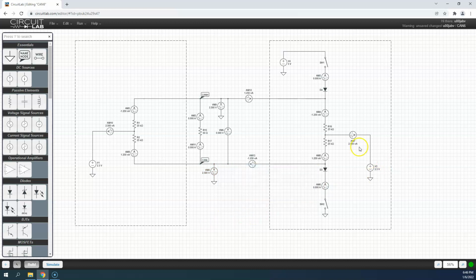But still, there's just a minimal current. This is nanoamps. This is 10 to the -9th. It's very small. It's got a bunch of zeros in front of it. Your meter wouldn't even measure this. You don't have a meter that's accurate enough. A Fluke 87, none of those are going to measure a nanoamp. So we could see, though, that when I do put the meter in place, I do have some current flow.